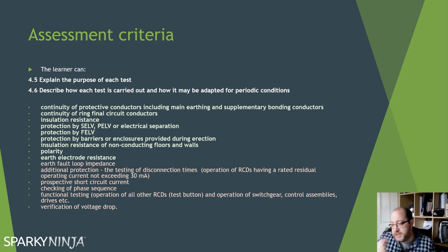For an existing system, though, for a periodic, we're thinking mainly about maybe some mechanical damage, but it's most likely going to be things like moisture ingress or heat damage. So we will still test it as much as we can. There will be a big excuse in the periodic world that we have to limit this test because we can't take stuff out of line and from between line and neutral. That's fine. You can always do those two in parallel to earth. You'll still get live to earth that way. So live to earth should be achievable.